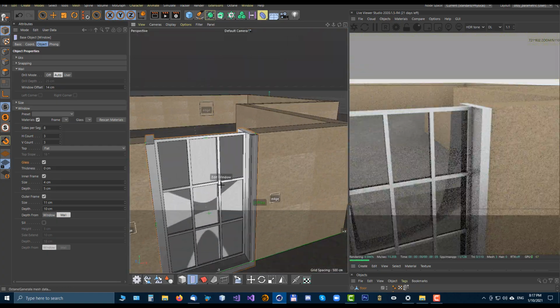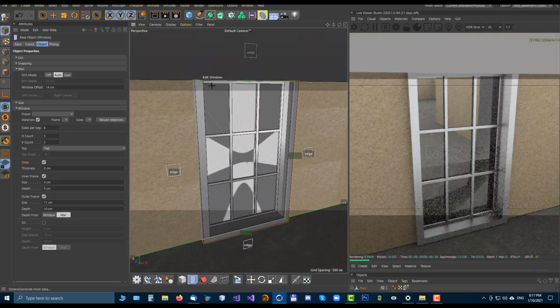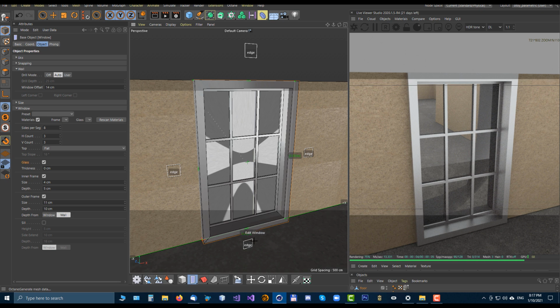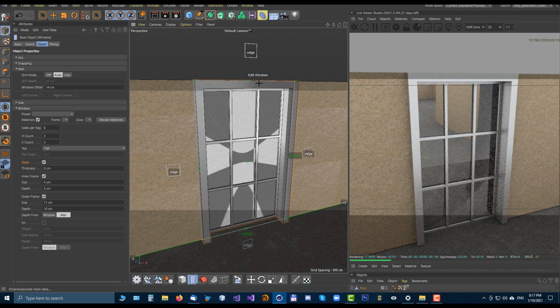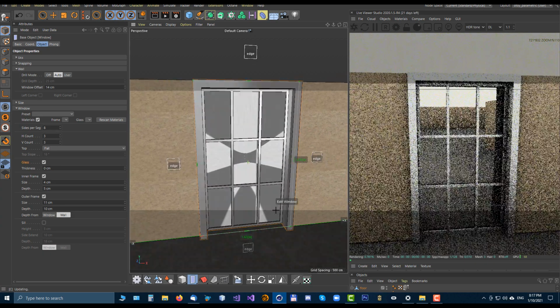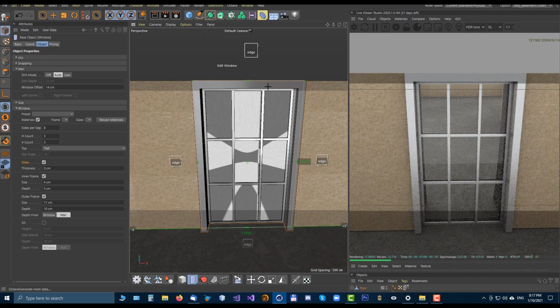Another neat feature of outer framing is that you can enable outer frame only to specific edge. So let's say I want this up, left, down, and not up, left, right, and not down framing. And this way you can create U shape of the outer frame.